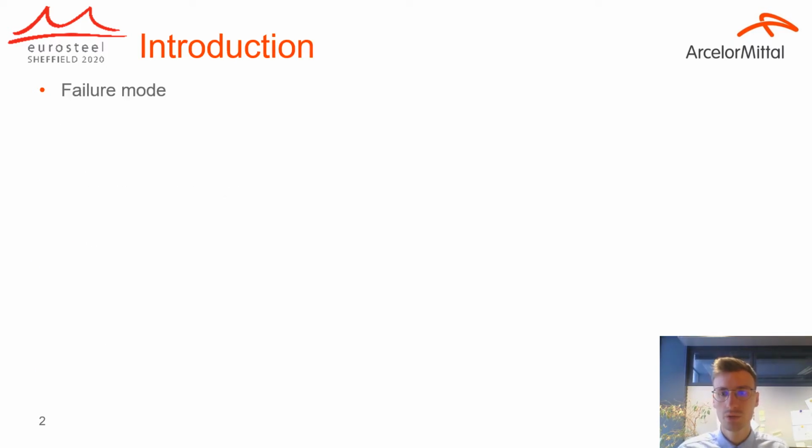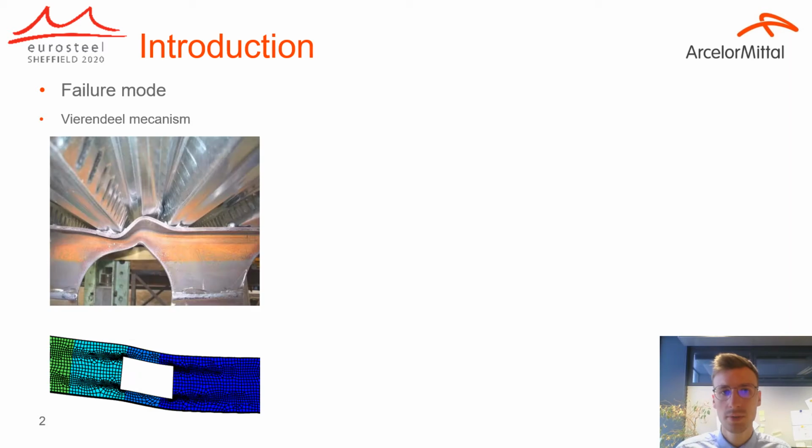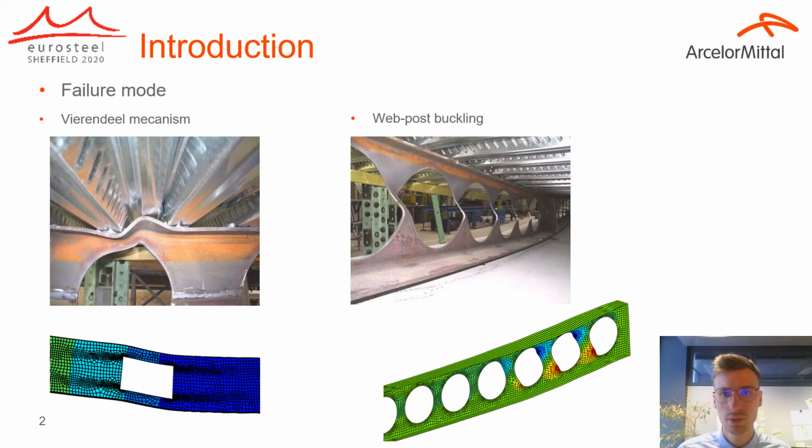So here are the two additional main failure modes we have to consider for cellular beams or beams with web openings. The first one, as you can see here, is the Vierendeel mechanism, and the second one is web post buckling, which is the focus of this presentation.